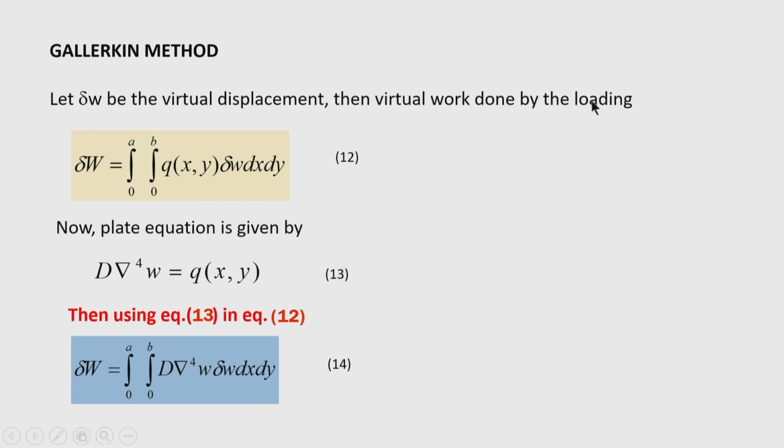Then the virtual work done by the loading is equal to a double integration, which is required because the plate extends in the x as well as the y direction, of q(x, y), the load applied on the plate, times del w, the virtual displacement.